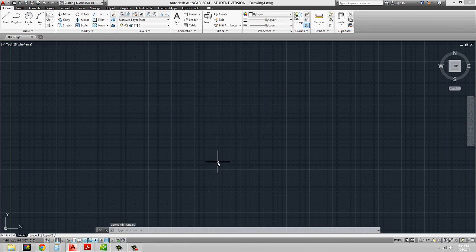Okay, so this is the first step that I typically do whenever I enter a drawing. Now, it gets a little bit tedious if you have to figure that out every single time you open the drawing. So what we can do is change that information and then save this file as a template file so that we don't have to keep doing that task every time we open a new file. So to do that, I'm going to go into Save As.